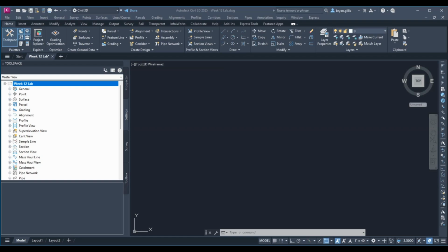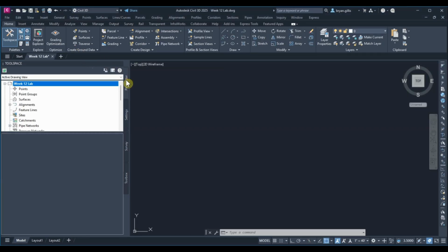Now that your boundary sketch is complete and validated in ArcGIS Pro, it's time to bring that work into Autodesk Civil 3D. This step bridges the analytical world of GIS with the drafting precision of design software. You'll be importing your data, configuring coordinate systems, and preparing your base drawing for the work that follows. All right, so this will be Practical Exercise 1, Importing and Preparing GIS Data.